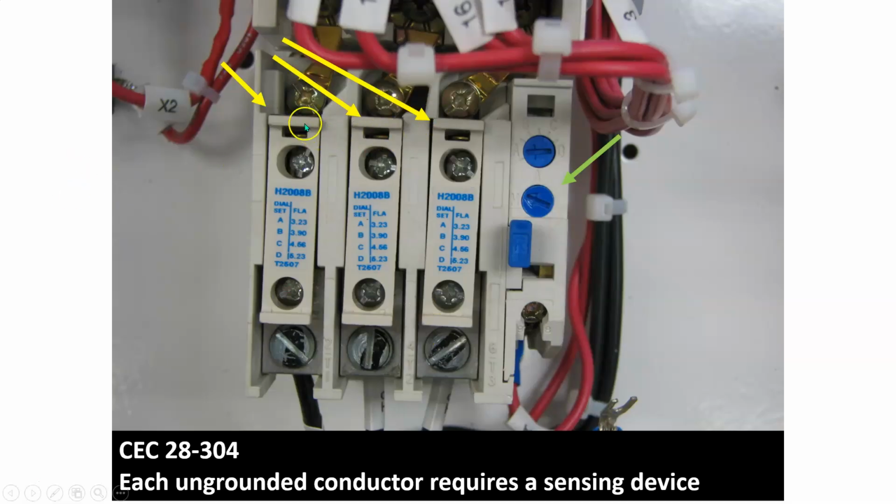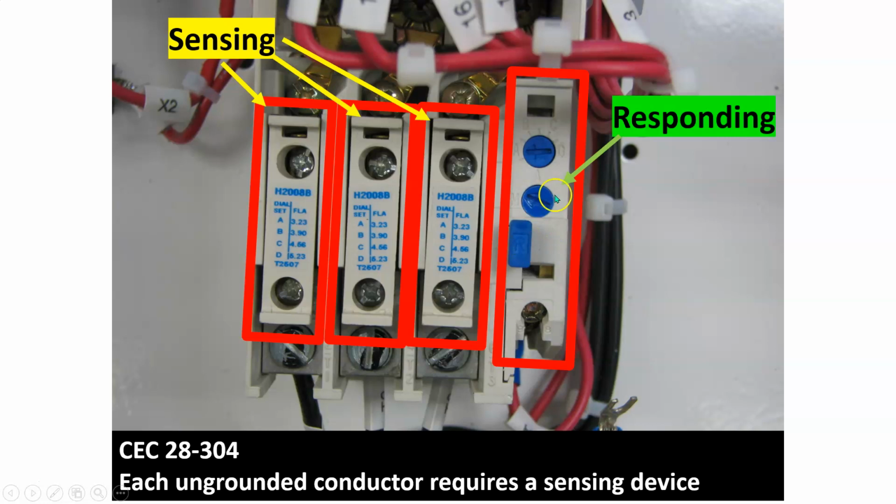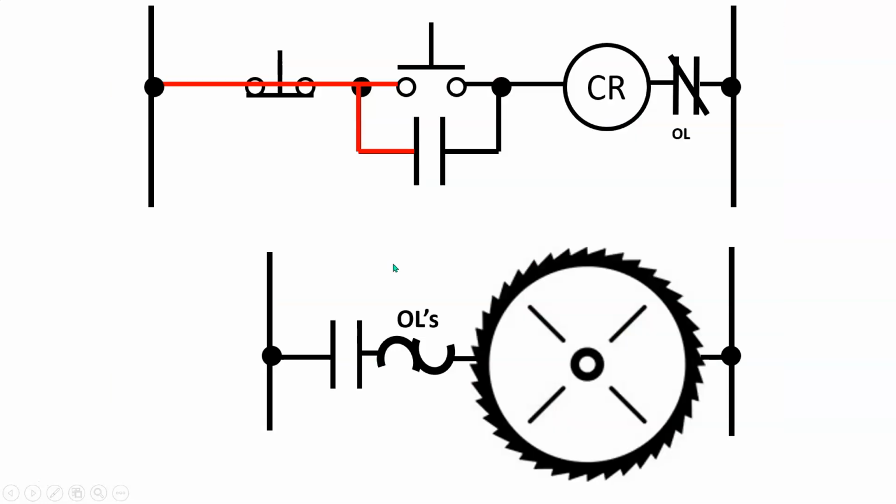All right, so here's an actual overload. These are the sensing devices, the actual overloads. And these are your overload contacts in here, which can be set to different loads. But this is what's actually going to be opening up and killing the power to your coil, thus turning off your motor. It says each ungrounded conductor, that'll be your line 1, line 2, line 3, requires to have a sensing device in them.